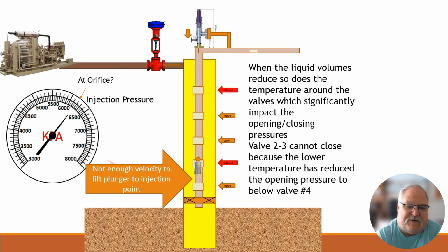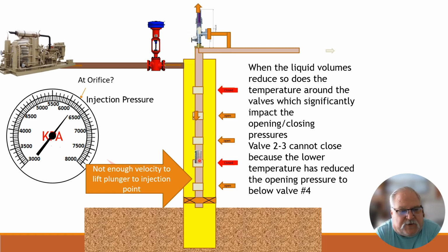up the gas. In fact, you might want to try to reduce the gas, because if I inject less up here, it might move quicker from this point to this point, and so it might actually do a better job. So don't get stuck on this idea that you need to have a plunger up in 12 minutes or something, especially if we've identified there's an issue up hole.